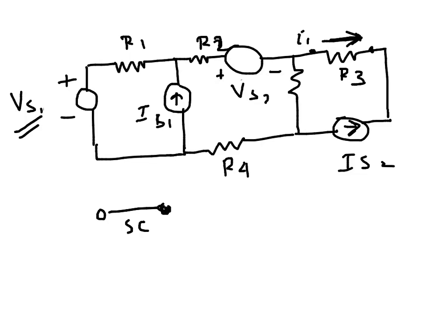Similarly, the definition of a current source is that it maintains that current through the source. If we look at this current source IS1, by basic definition, whatever it is connected with, it should maintain IS1 through it. Now, in order to make it inactive, in order to make that current flow stop, we can open it. So making a current source inactive is in effect making it an open circuit.